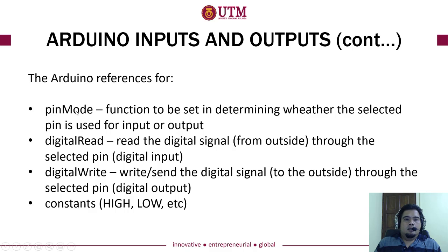And then we also have digitalRead. Once you have set a certain port as an input port, especially a digital input port, by executing the pinMode function, then you can use digitalRead to read the value from the outside into that port.